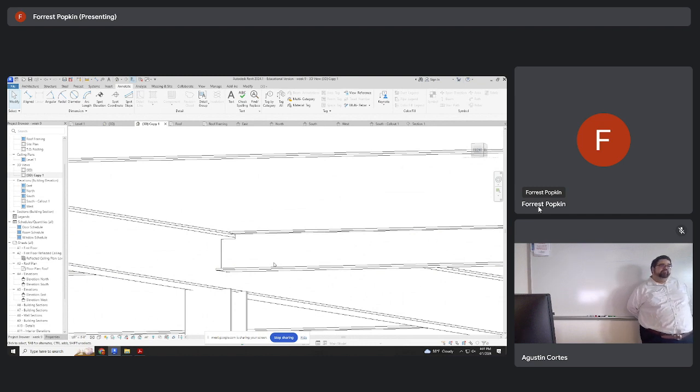It's leveling. So if I have just a plywood substrate and I have nothing above it, if there are little deviations in the height or little slopes, if I pour something liquidy that gets in to where it needs to go, it will be what's called self-leveling. And self-leveling is particularly important in commercial applications where I can't really afford to have an eighth of an inch differential if there's ADA issues and it's going to feel bad and certain finishes are not forgiving, and so on.